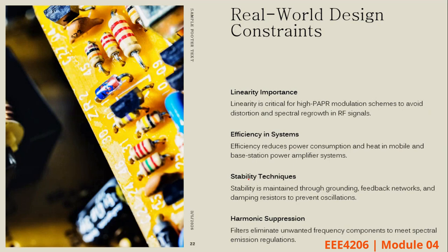And finally, we must suppress what you call unwanted harmonic signals using filters. So this is where you have the low pass filters, to comply with spectral emission regulations, because sometimes there are unwanted signals or there is some noise.